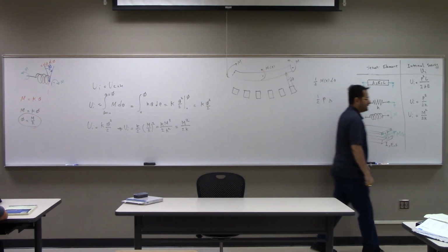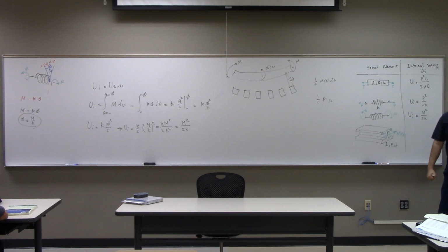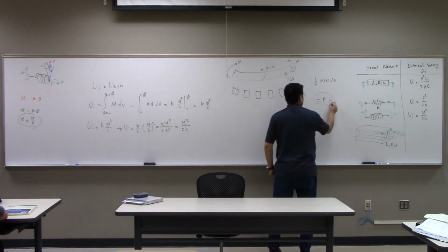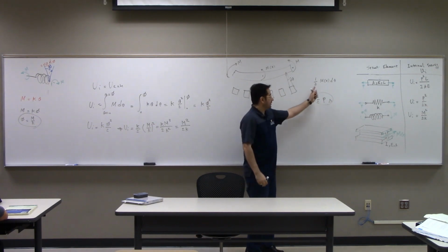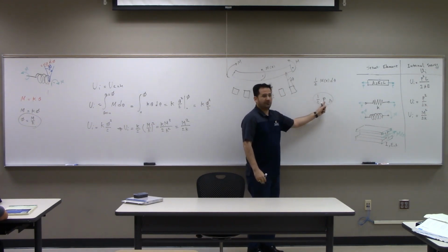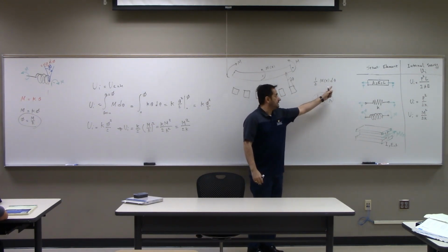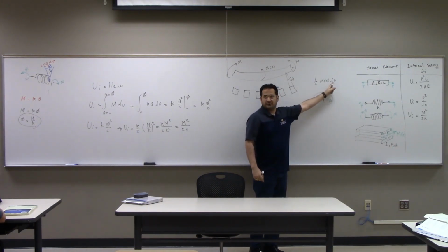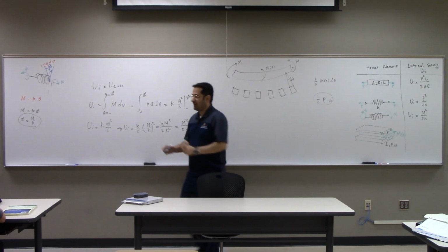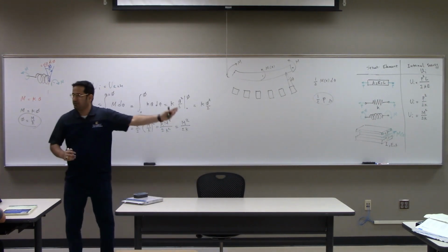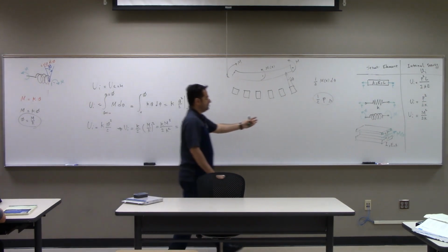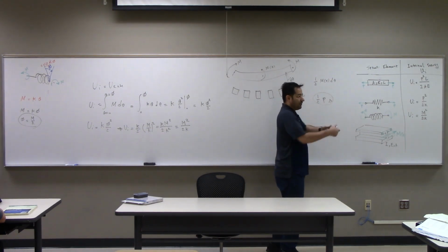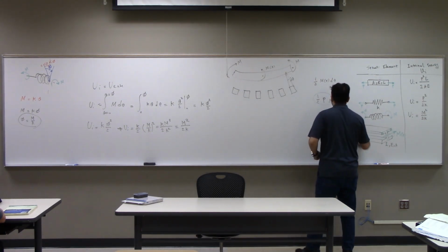We computed the area under the curve, and it became half of P times delta. Remember that? So that's exactly the same analog. Instead of P, you got moment; instead of the linear deformation, you got angular deformation, d theta. That's exactly the same. So how do you find it? You just do exactly what we did last class, but this is just rotational, M1.